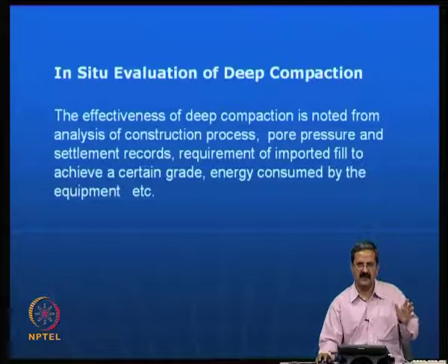You have done a few tampings now, so when do you release the weight the next time? You can get an idea from the pore pressure and settlement observations so that things are effective. If you keep on tamping without understanding the pore pressure response, it may not be very effective. But if you understand that the pore pressures have dissipated to some extent and then tamp again, the sequence of tamping can be properly optimized.